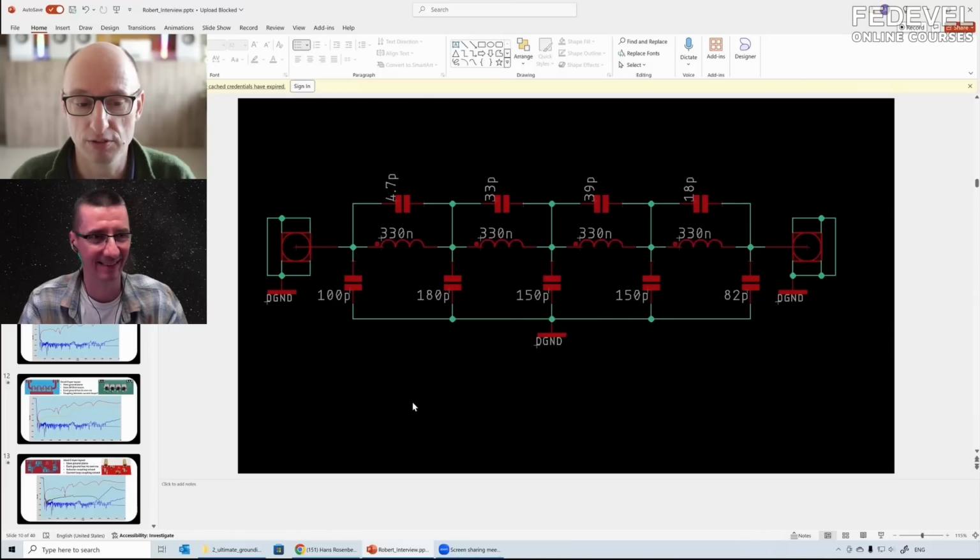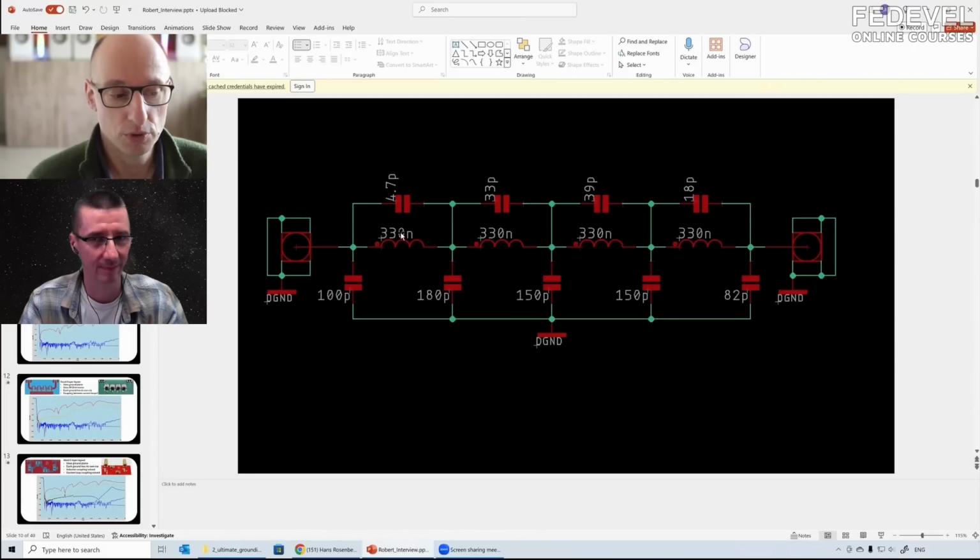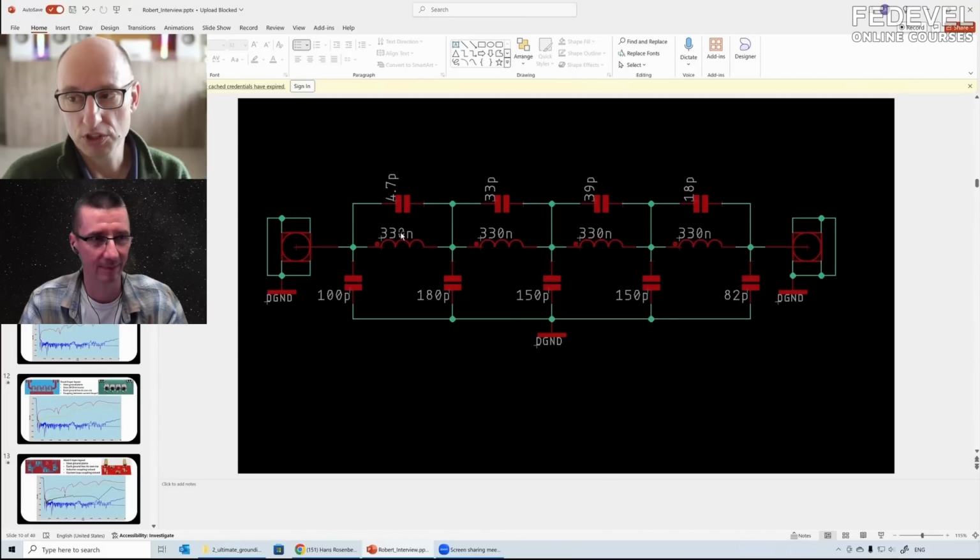Now, this is basically the filter. The signal enters here, it's a 50 ohm filter, and the signal exits here. The bandwidth is roughly 30 megahertz. And you see all these taps to ground, which short the signal in stages. And you see a number of parallel resonators. Each parallel resonator at its resonance frequency will block the signal, so you get a whole bunch of frequencies at which the signal is blocked. And the rest of these capacitors take care of an overall suppression characteristic.